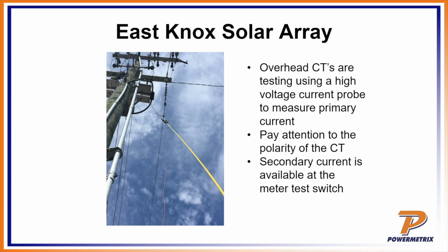As part of a transformer rated site, it's important that certainly we test our instrument transformers as well. You definitely want to test your CTs. I'd want to try and test your PTs if you have the opportunity. But the thing to pay attention to here, of course, is once again, how's the meter wired? In other words, you have to be careful of the polarity. Make sure that the polarity of your high voltage current probe is pointing in the right direction. Otherwise, you'll get a phase error when you run your CT test.